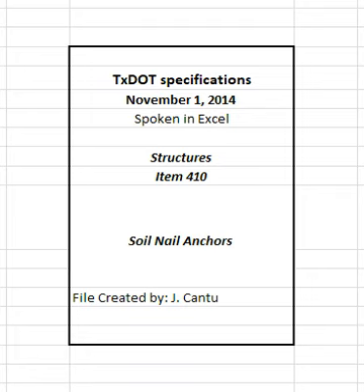Unless otherwise shown on the plans, the verification test nail acceptance criteria is: the total creep movement is less than 0.04 inches during the final 10 minutes reading increment. If movement exceeds this value, the engineer may require an additional hold period of up to 60 minutes with a maximum 0.08 inches total creep movement, including the movement from the original 10 minutes hold.